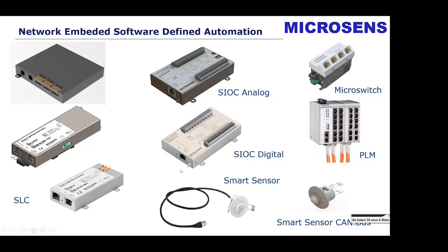In the middle, we have our smart I/O controller. These devices are also PoE fed, so you have only this RJ45 connector. On this device, you can connect conventional devices, for example, analog sensors, dry contacts. You can run, for example, a valve, or all devices which could be controlled by 0 to 10 volt. And this means we support all the standard signals which are provided for sensors and actuators on the market. And over this device, you can connect conventional field components to the network.